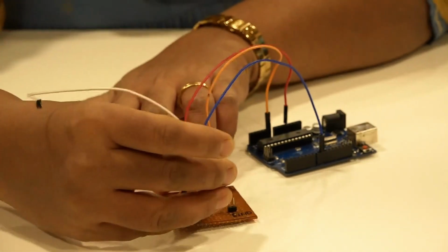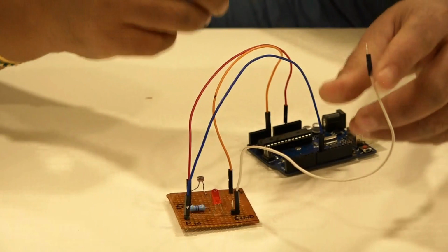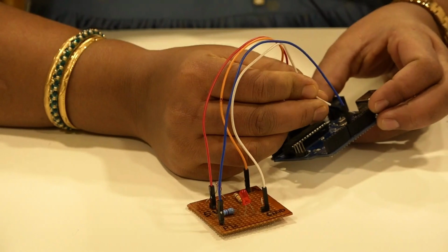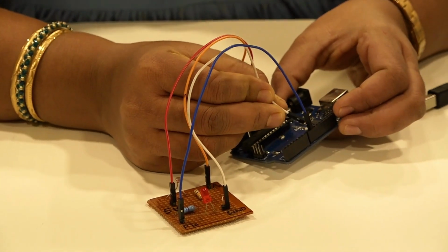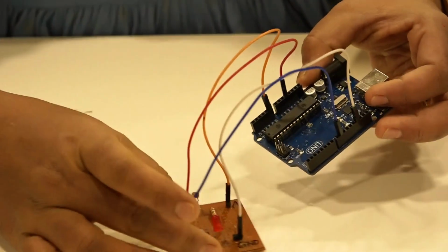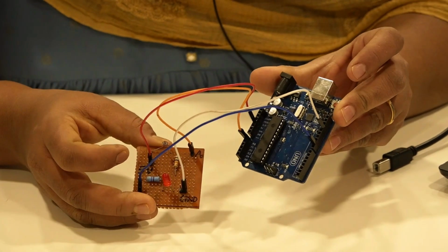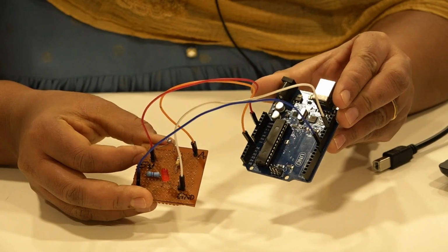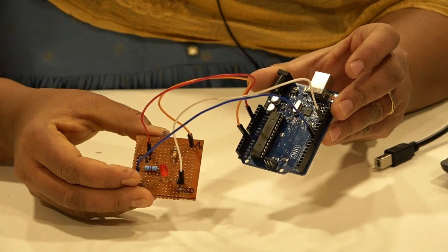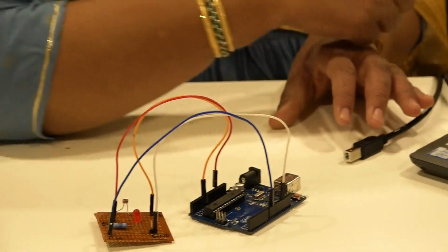And next is the ground connection of LED. So you can choose any of the ground connections here. 14th pin will be a ground pin. So these are the connections. So one leg of LDR you are connecting to analog signal, another leg of LDR you are connecting to 5 volts. In the same way for LED, 2 legs, one leg is for ground, another leg is for digital pin. So whatever pin number you are writing, it depends upon the program.